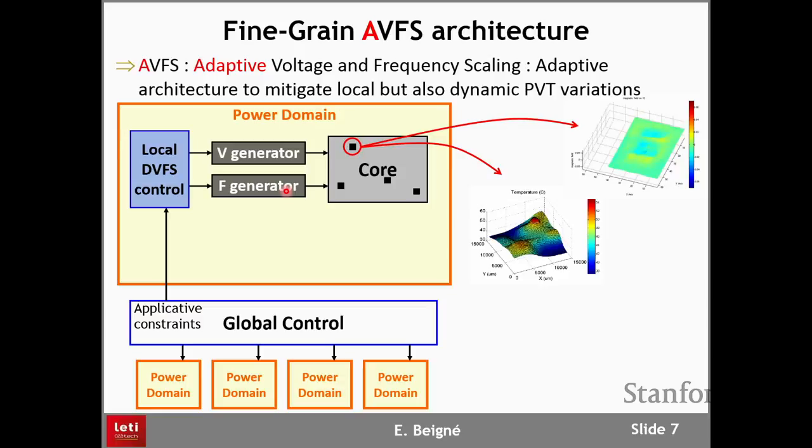Okay, great. We had the same issues when we wanted to have local frequency generators, because we went to people doing RF and they were providing a wonderful PLL, which was maybe 10 times the size of the core here. Okay, so we've been able to go finer. The interesting idea here is that we don't need to know the absolute temperature. We don't need to know the absolute value of the voltage. What we need to know is that these values are changing. So really simple sensors giving you dynamic information of what is happening in the core is really enough.